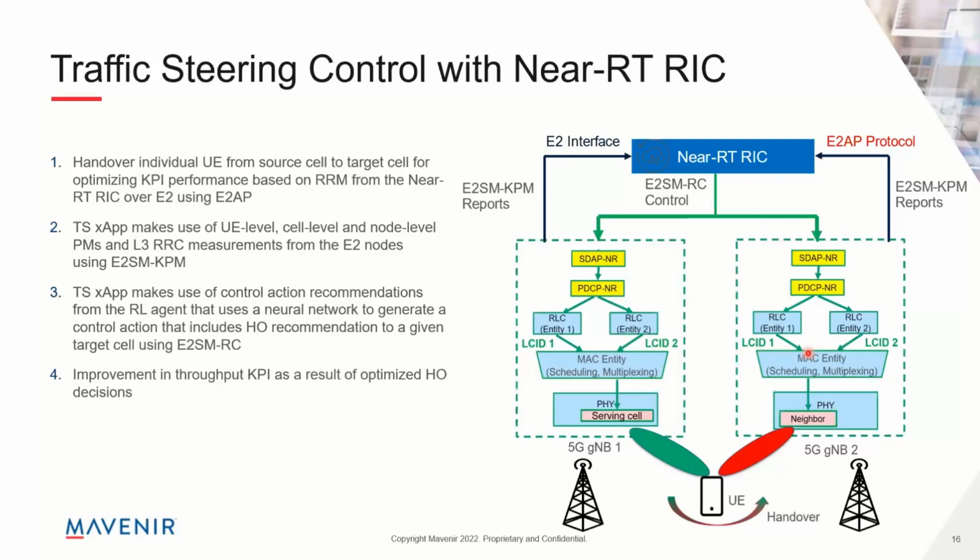With real time, whenever you don't have traffic, you can intervene and shut down maybe the PRBs or some carriers, and as soon as you get traffic, you can turn those carriers back on. Or using non-real time, you can differentiate between daytime, the busy hour, and the non-busy hours. Those are the kinds of demands we see as a solution provider in the industry today.